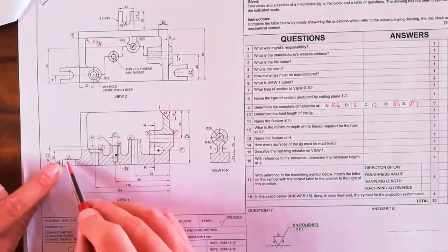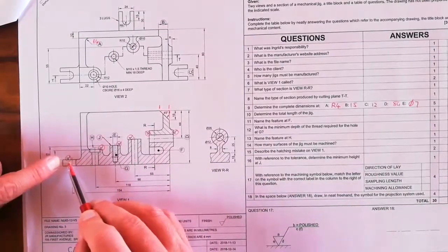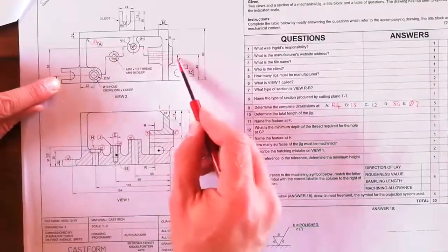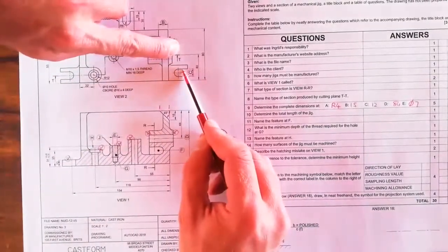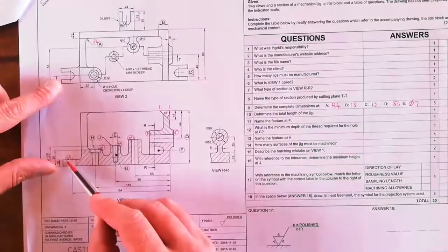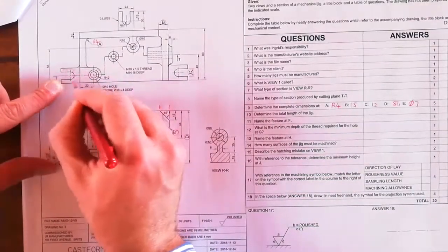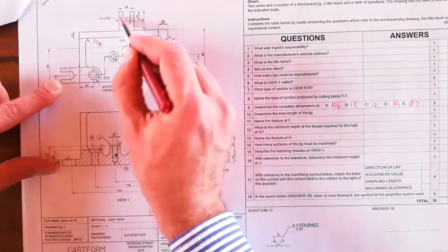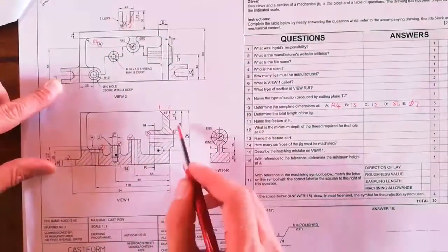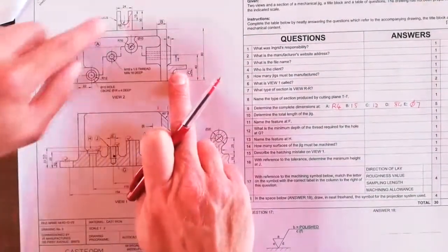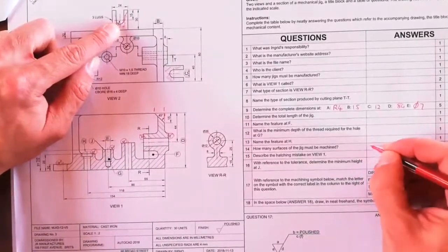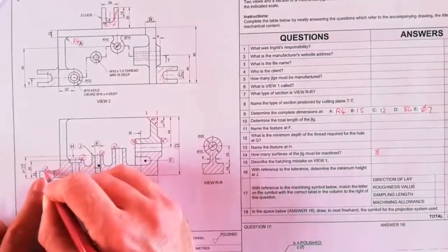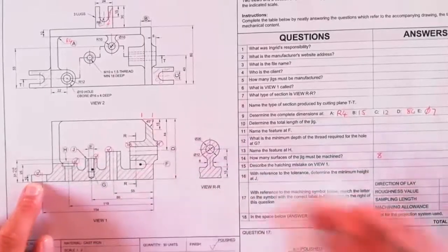Look at this quickly. Do you see here that this part actually refers to this part of this component? But because of the cutting plane, this one is excluded. So if this surface here is machined, that surface must be machined. So we're now up to 7, plus this is again the same. So we've got 1, 2, 3, 4, 5, 6 plus 7 plus 8. The correct answer here is 8. So make sure you don't just write the easy answer, but see which surface each one refers to, and if there's more than one, you have to count that with it.